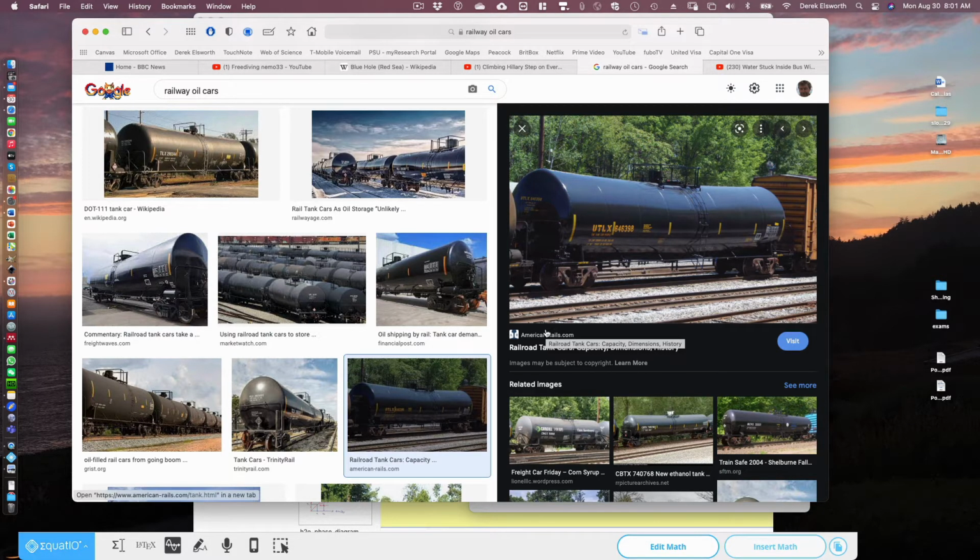The reason for that is if you take water in a container and you accelerate with it, it's like putting a bulldozer in the surf zone in the sea and going along. You'll get kind of a bow wave. It's no different from a boat forcing its way through the water. You'll get a bow wave that's elevated. So as you start moving a tank, the acceleration, not the velocity, but the acceleration of that tank will tend to push the water to one end. It will rise because it can't get out of the end. And if you don't have this little flare, then potentially you can pop off the lid.